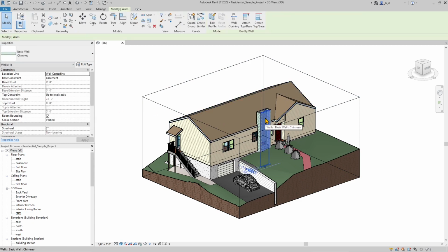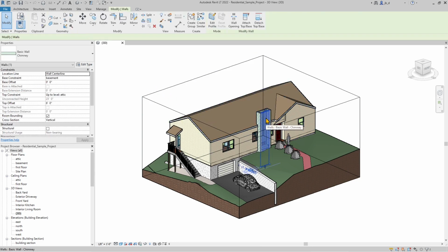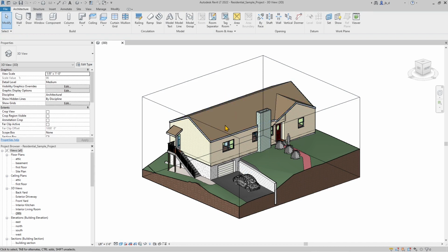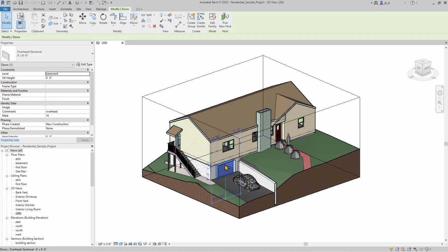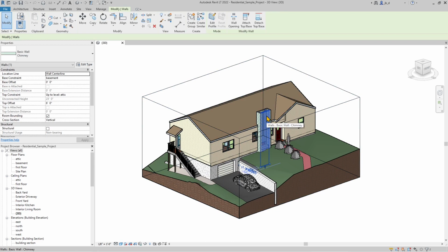Now, when you select something with the left mouse button, you can also deselect by clicking Esc on your keyboard. So if you press Esc, you're going to exit that particular command, which is a selection basically. Okay, now when you roll over an element and it's highlighted in blue, this means that it is pre-selected. So then to select it, you need to click it with the left mouse. So roll over, pre-selection, click once, it's going to be selected.